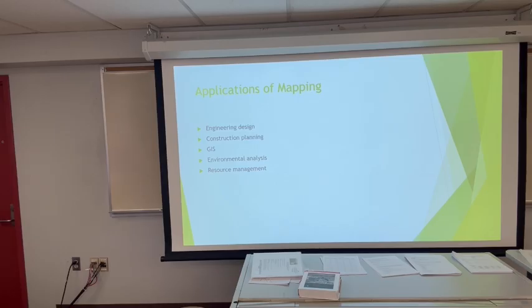And also with construction planning, once the engineer has developed a set of plans, there's usually some earth moving going on, cut and fill. So for construction planning, they will look at those plans and say, okay, how much dirt do we have to move? How much cut do we have to make? How much fill do we have to make? Where's that cut going? Where's that fill coming from? Do we have enough? Planning in that instance. So engineering, design, and construction planning can go hand in hand at times.